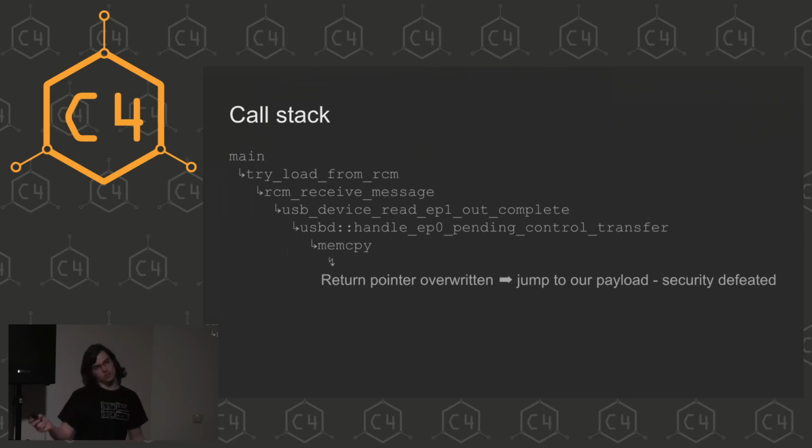And the transfer never completes because we just tell the boot ROM with that length field that we want to send, I don't know, 20 kilobytes of data, but we only send 19 kilobytes. Or 20 kilobytes minus 1 byte. And then we just stop sending stuff.